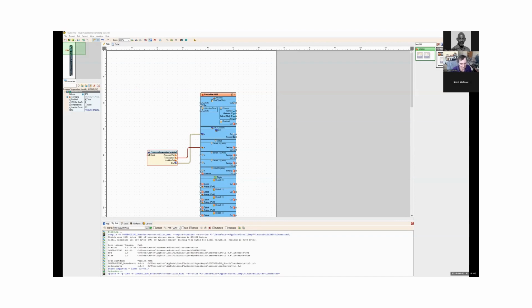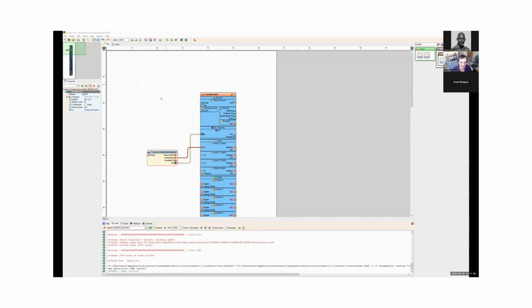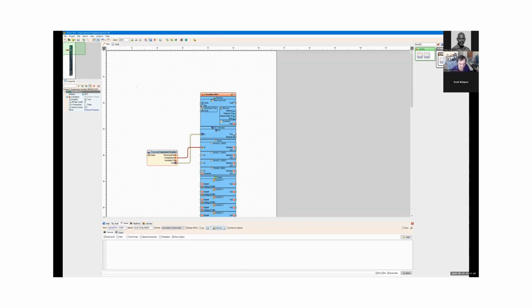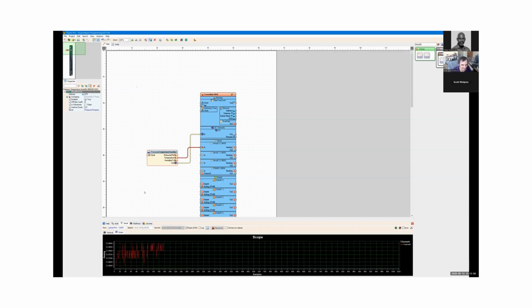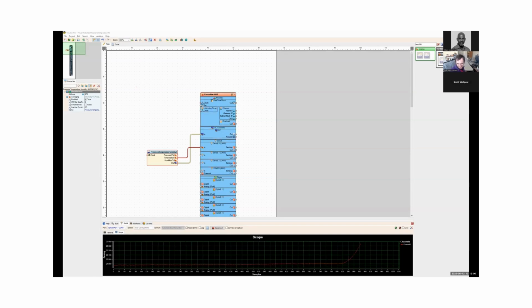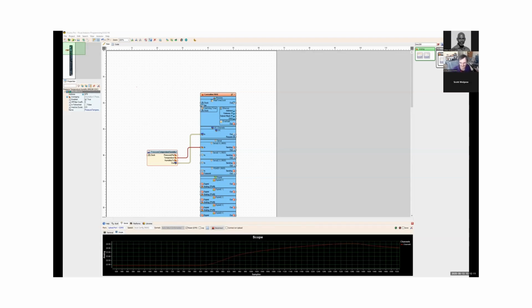So it's uploading at the moment, compiled and uploading. Okay, the code is uploaded. And if I go to serial now and connect, we should start shortly seeing the temperature coming on it. Okay, here is the temperature. And if I touch the sensor, you will see the temperature starts rising immediately. So we have, yeah, and when I release it, it returns to normal temperature. So we have a temperature sensor.